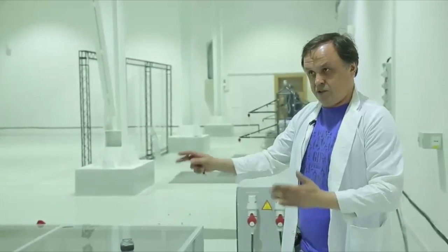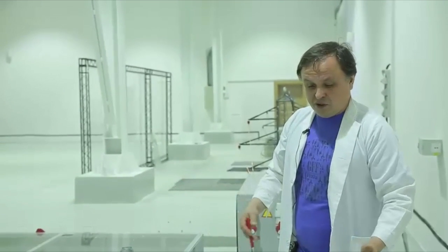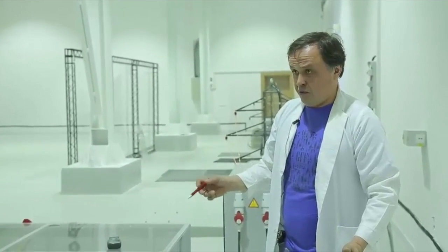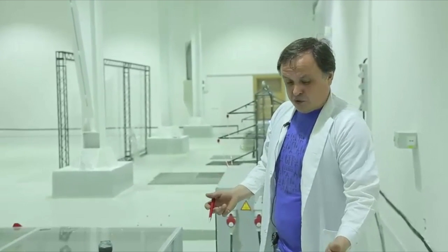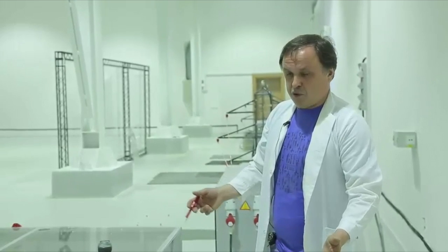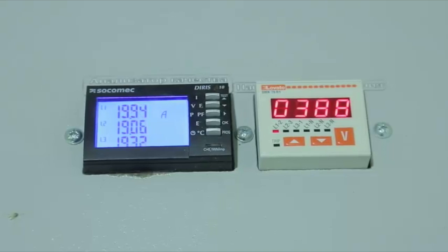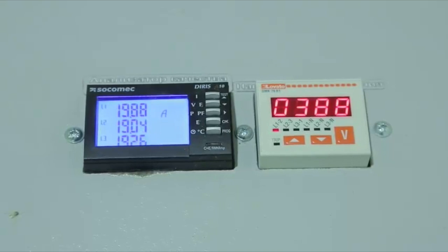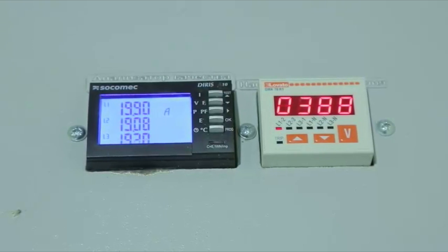Another know-how. Let us introduce a unique phase stabilizer of SFN type that allows asynchronous motors to perform continuously, as well as allowing motors to start and slow down gradually during part-phase modes, and with that to work in the energy-saving mode. Let's start a standard asynchronous motor of 18.5 kW in the energy-saving mode.